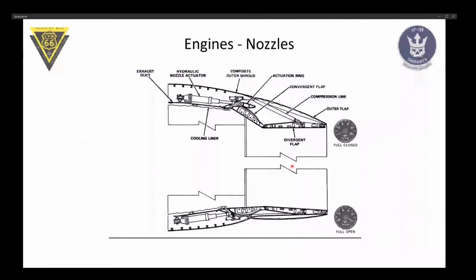Now, as you may or may not know, the thrust that an engine produces is a product of the mass flow that goes through the engine and the exhaust gas velocity. Now, the mass flow is more or less fixed because it depends on our compressor size, fuel flow, and whatnot. But the engine exhaust velocity is something we can influence. And the way we do it, we're building a nozzle here, because the nozzle constricts the available cross-section area.